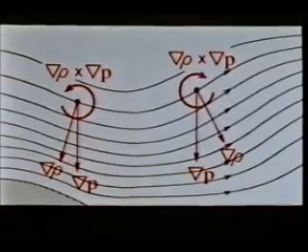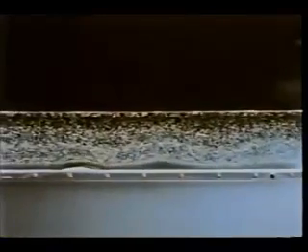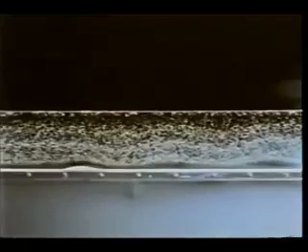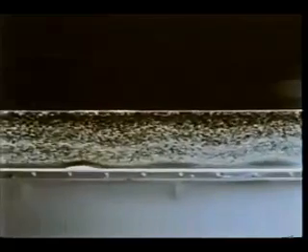Of course, these waves can also be explained from a buoyancy force viewpoint. The descending fluid particle finds itself in a heavier environment and is forced back up as it moves along. It overshoots, then descends again, and so on. When the barrier is small, the waves have small amplitudes, as we have seen.